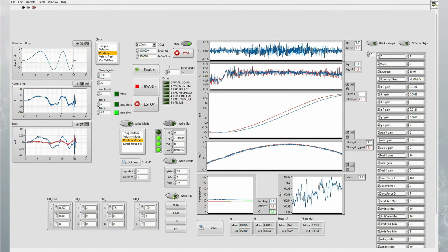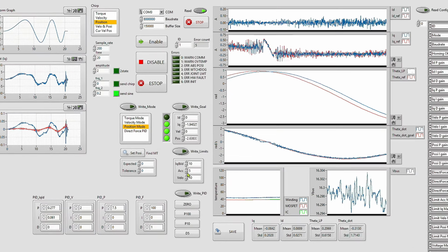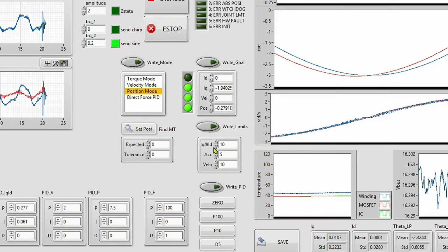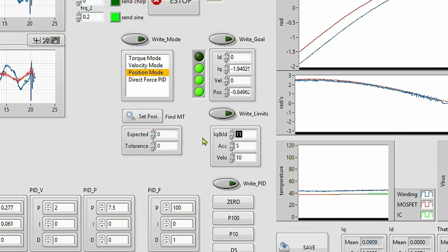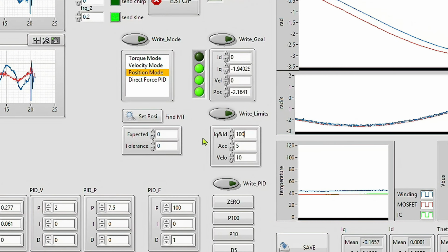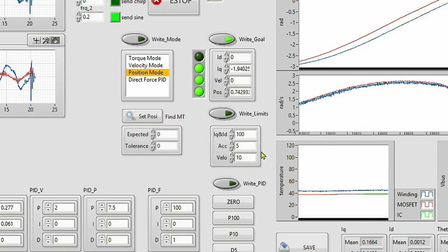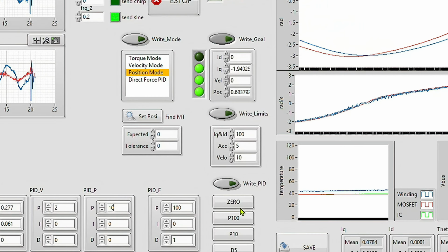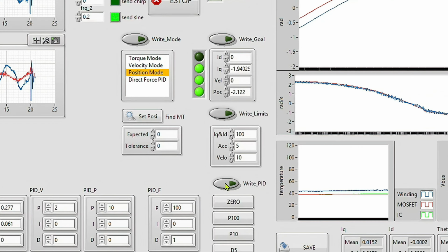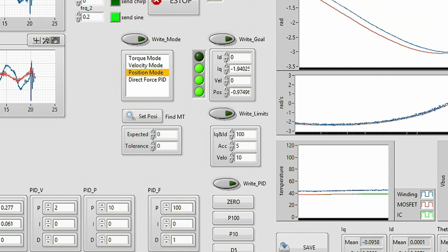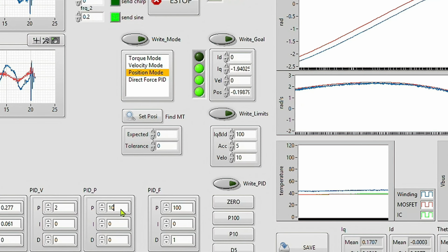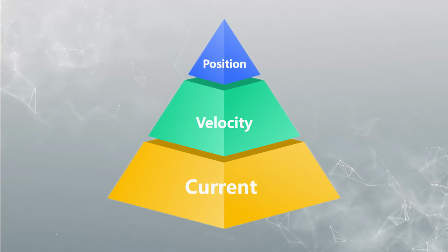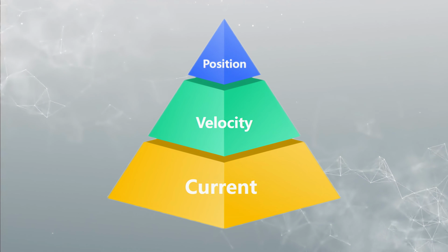Finally, if your tracking gains feel dialed in but the joint still yields or sags under heavy external or gravitational loading, the issue likely isn't your loop tuning. It is often that your limit I max register is set too conservatively, bottlenecking the maximum output torque capability of the underlying FOC coils. In summary, avoid treating cascade tuning as a rigid, unyielding formula.